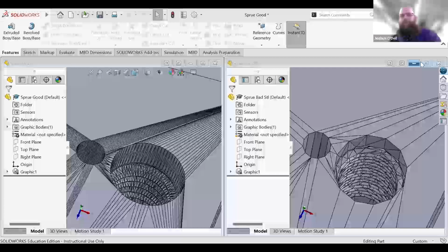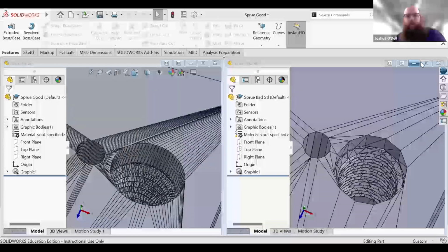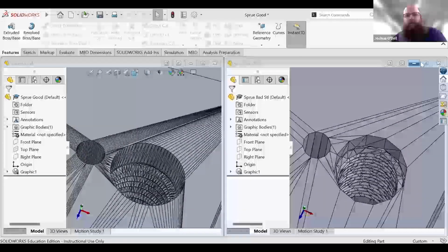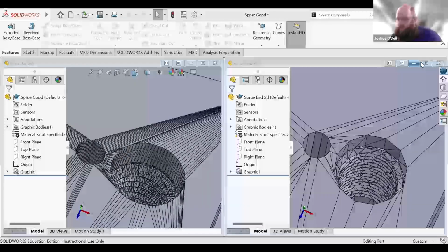So I talked about it a little bit after the FFF pattern discussion. If we're using FFF patterns, we're using pretty much exclusively PolyCast because it was developed to be used in investment casting, so it has a lower ash content. We haven't done any expansion tests on it yet, and I'm going to add it to my list now, because whenever we test a new material for investment casting, that's one of the things we baseline to see how much it's expanding when it's heating up, to see if it's going to crack our shell.